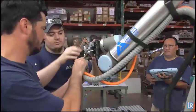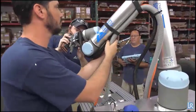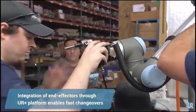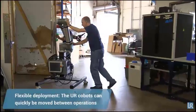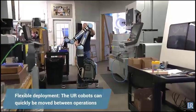To support a high mix, low volume environment, we have to achieve quick changeover. We have gone back to the UR+ program that will allow us to put different tools onto the part for different deburring and sanding operations, and everything can be done very quickly. We can't dedicate our machines to one particular part. Another advantage of a collaborative robot is that I can move it to another location and reuse it.